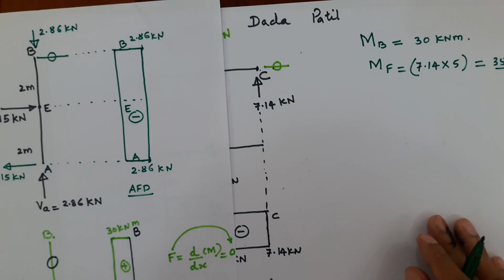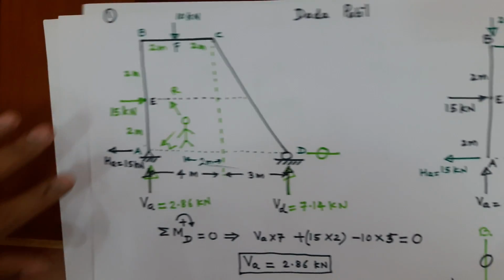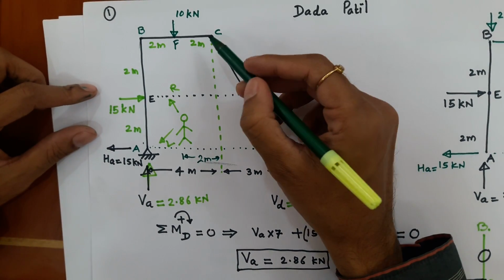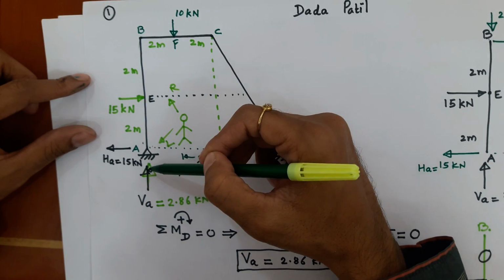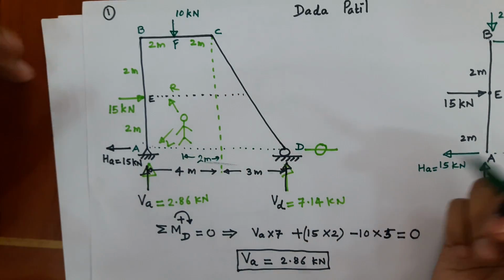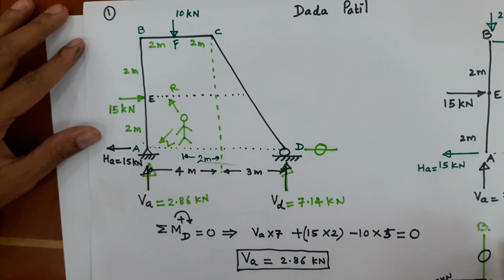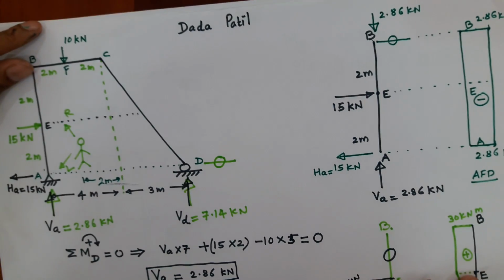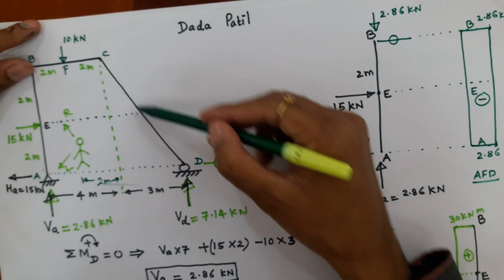Now coming to bending moment at C. Again I can go back to the main diagram. Again, as per the definition of bending moment which you all learnt in strength of materials, either I can consider part C of BEA or CD. But again, there is no point in considering C of BEA, that is time consuming as well as there are chances of making mistakes. So to save time and not make mistakes, you can consider part CD.